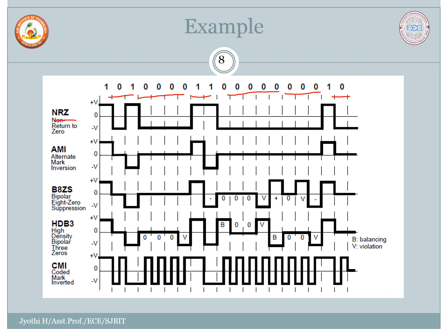By using the non-return to zero polar technique, 1 is going to have the positive amplitude, 0 is negative, again it is positive, and it is going to be transmitted with DC. 0 is transmitted with the negative amplitude for 4 zeros, again it is positive amplitude, here it is positive, again these are all negative amplitude. Okay, so then it becomes positive, and here it is negative.